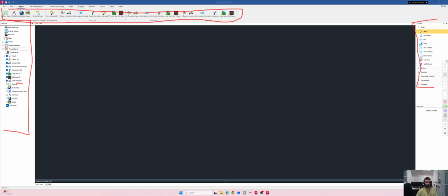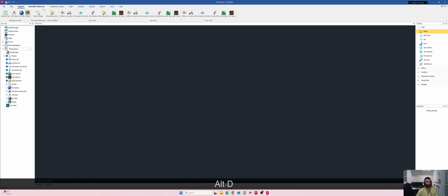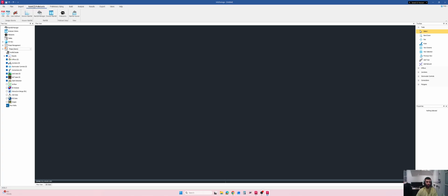In the top tab, you can see this plane, and I will just turn off my draw mode. You can see this one is the rainfall and pollutants. Here I have the FSR and FEH design storms. FSR and FEH are the design storms usually used for the UK. And if you are working from Australia or USA or somewhere else, you have to change your preferences and change your region.